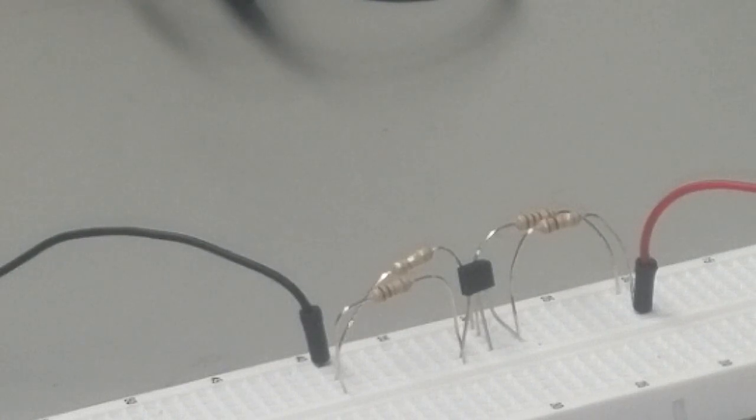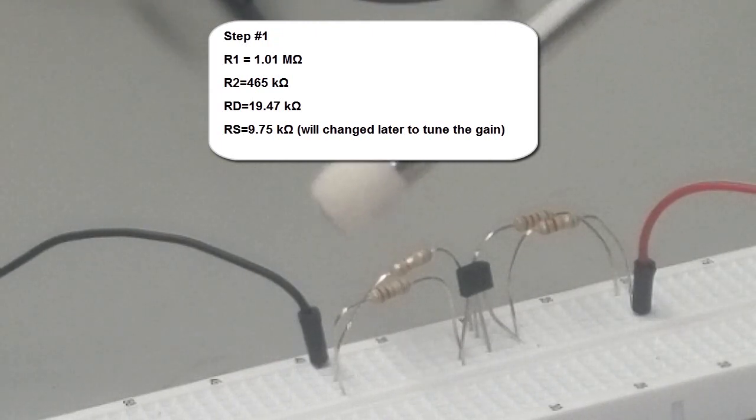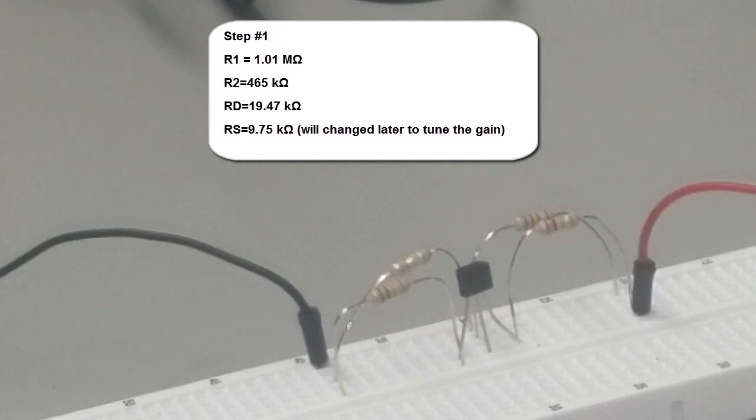So based on the measured values, R1, which is this top resistor here, should be 1 meg. When I measured it, I got R1 equal to 1.01 mega ohm. R2, which is the one that goes to ground, this resistor over here, is supposed to be 470 k ohm. But I got 465 k ohm, 465 k.